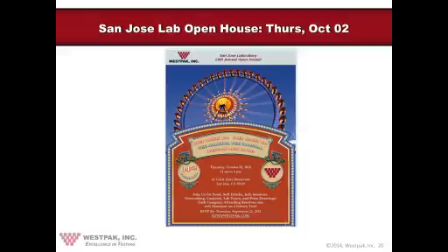So it's not just small parcel. The 3A is for small parcel. The 3B is for large packages and large crates. The 3E is for unitized loads and so forth. So the 3 series tests are the general simulation, and all the 2 series tests are the partial simulation. They no longer differentiate between international and domestic, because we find through some recent studies that when packages travel internationally, either by vessel or by air, the vibration in the test inputs isn't as bad as previously thought. The worst case for any package, even temperature, humidity, vibration, shock, is the truck route.